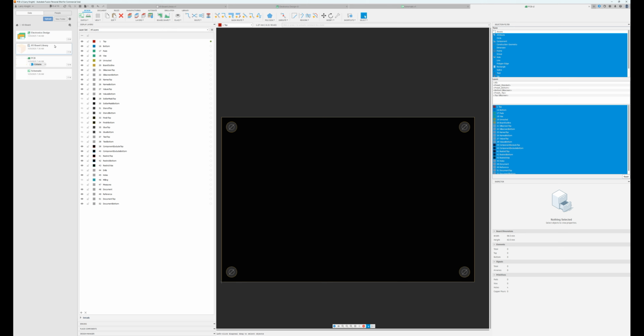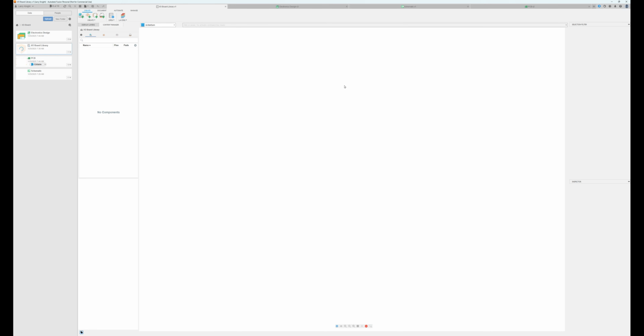So now, the only other thing we need to do first, before we start drawing a schematic, is import parts into our library. So let's double click on the library. We need to have parts to put in the library. The very first thing we have to put on main brain is the I/O connector. And then from then on, it's anything goes, whatever you want to do. But the minimum requirement is the form factor of main brain, and to get that I/O connector on there in the right spot. And then after that, we can start drawing a schematic.